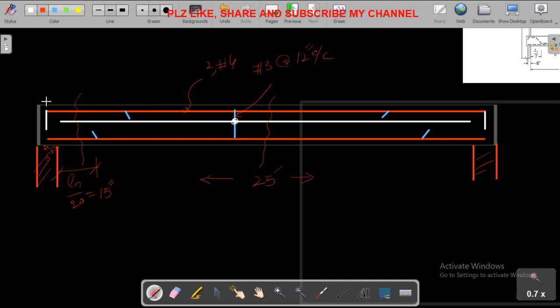And this top bar will be cut off from the face of the support, yes, from the face of the support for a distance of Ln by 4, right? So 25 times 12 divided by 4, it will give me 6 feet and 3 inches. Similarly for these two options as well.